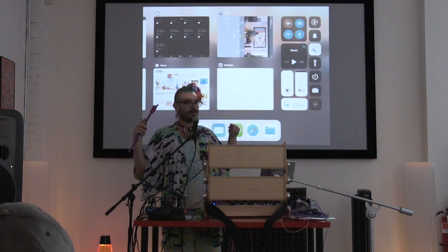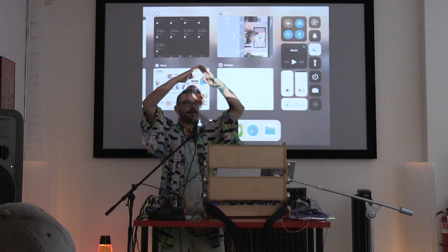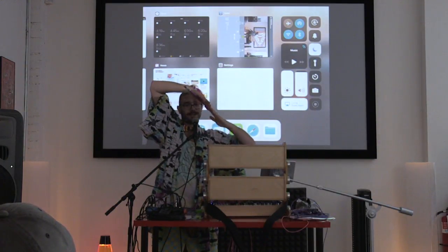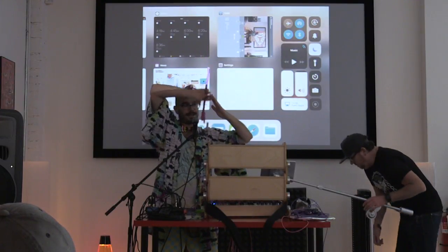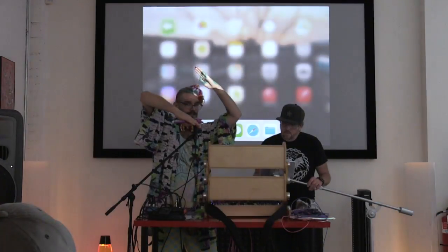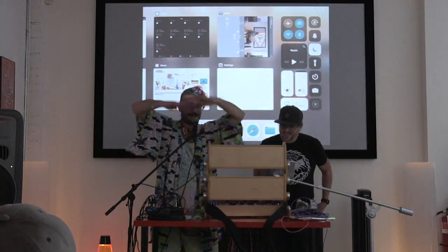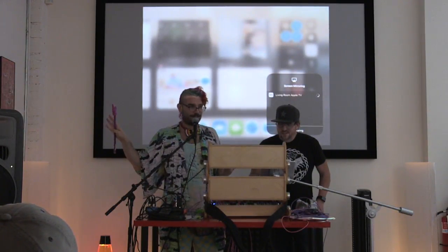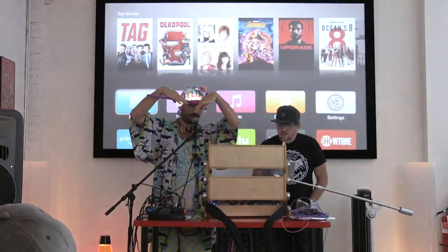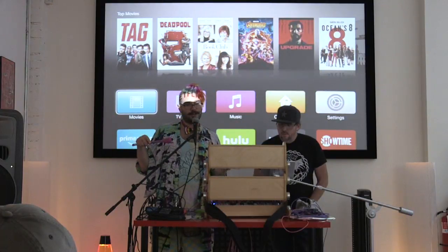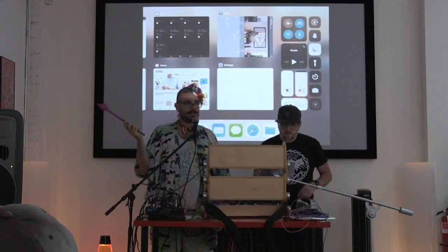So if you imagine a triangle wave, we fold the top of the triangle wave in, it makes a triangle wave one octave up. If we have a sawtooth, we jump the sawtooth back down to zero right here, we have a sawtooth that's an octave up. I literally did this for a physics project in school. I did the physics of techno, and I had all the waveforms and stuff. It's so much better than an oscilloscope, you know? So if we have a sawtooth an octave up versus a triangle wave that we're folding to be an octave up, you can imagine the difference in quality between a wave folder and a wave wrapper, being like the difference in timbre between a triangle wave and a sawtooth.